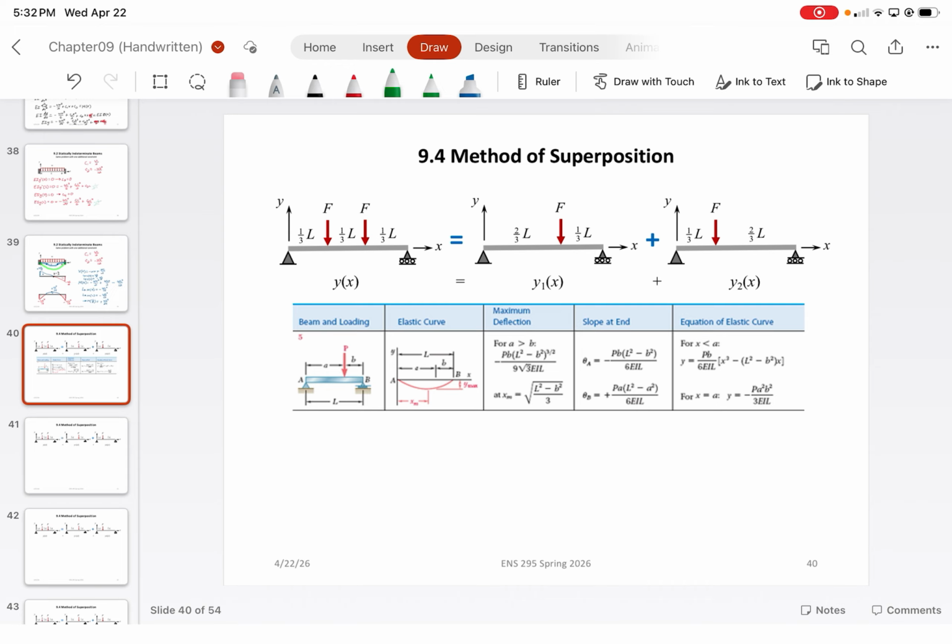So for this case, we've got 2 point loads located basically at third points from each other. And so when we use the deflection equations, we can find out the overall behavior of the structure just by summing the two loads and adding their points together. So in this case, we've got a point load y1(x) and y2(x), and so we could work those problems accordingly. So, for example, let's work using the first set of deflection equations, all right?